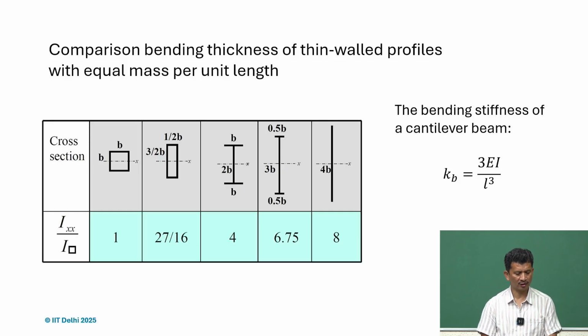So, in order to compare, suppose there is a bending load, what kind of sections, what kind of profile should we use so that we can maximize the stiffness? Of course, if we want a higher stiffness, we should always aim for a construction so that there will be forces in the longitudinal directions only. But many times it is not possible, and other kinds of loads will also come, like bending or torsional load. So, how to stiffen the structure in that case?